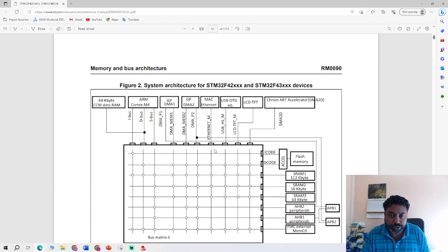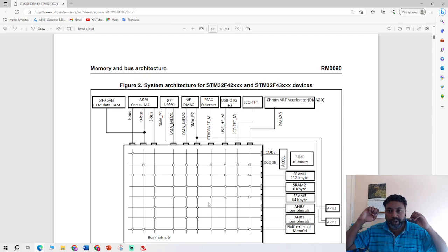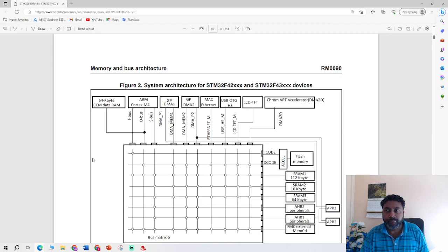And this is the bus matrix to show how the memory from the various buses is going to integrate and where it's all sitting in terms of the memory locations, like SRAM1, where it is sitting, SRAM2, and if it is connected to the high performance buses, where it's connected and how the memory is connected. For example, the system bus is connected to the high-speed bus. So this will give you the memory allocations, about when you send some information to save, where it goes and sits in your processor, and this is how it is.